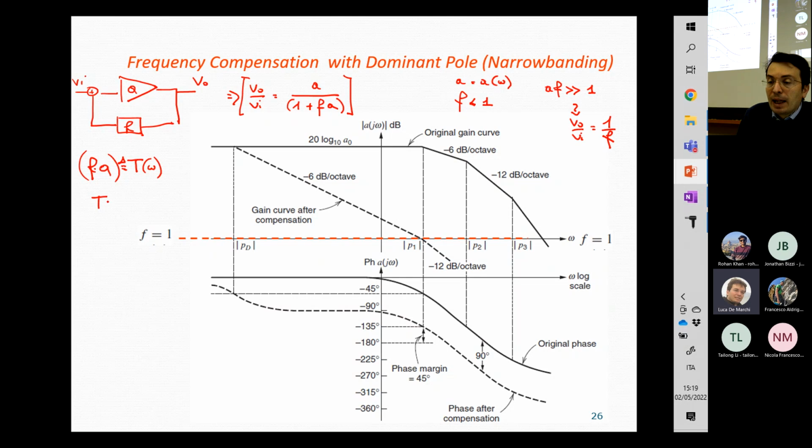If we find the so-called omega 0 dB angular frequency, where the modulus is equal to 1, then the phase of the loop gain can be fruitfully employed to investigate the stability: if the phase value is larger than minus 180 degrees, we do have stability.